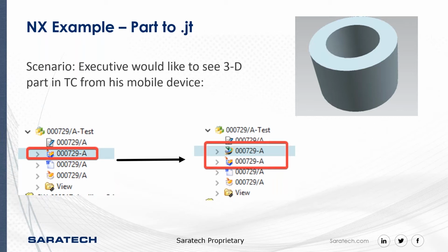So this is going to make things really easy within Teamcenter because you can see the parts and the assemblies as well as manipulate them to some degree for the information necessary. So you can take section views, you can take measurements and queries and measure surface areas if warranted. We can additionally take snapshots and create markups so that we can comment and pass along that information to further participate in change orders, any sort of review processes, or really however our business sees fit.